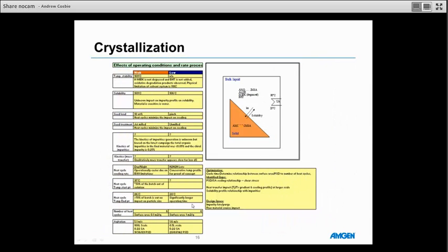With this information laid out, they moved on to the engineering assessment phase. They posed a challenge for optimization. So they wanted to determine the relationship between surface area and number of heat cycles to make sure they had an optimized process, as these heat cycles could really increase the cycle time of the process. They identified knowledge gaps here, one of them being heat transfer impact. So we're doing heat cycles. They want to know, at larger scale, would they be able to keep this cooling profile with the increased length scales and heat transfer? And they wanted to develop design spaces.